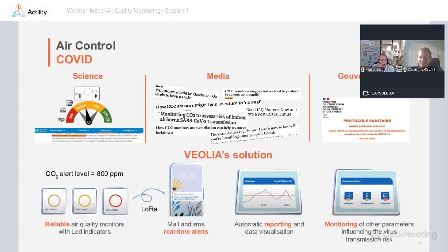So it was indeed for LoRa coverage. So, for LoRa coverage, I know on our side, people go around with trackers. This is a small one, you have bigger ones. It is sending a calibrated signal. And the network is measuring the signal-to-noise ratio, which is key in LoRa. You know, in LoRa, it's really the signal-to-noise ratio that's important. And based on the location and signal-to-noise ratio, we build color maps of where it's well covered, not covered. We also provide statistics on packet error rate. And as Mireille was saying, LoRa makes it very, very easy.